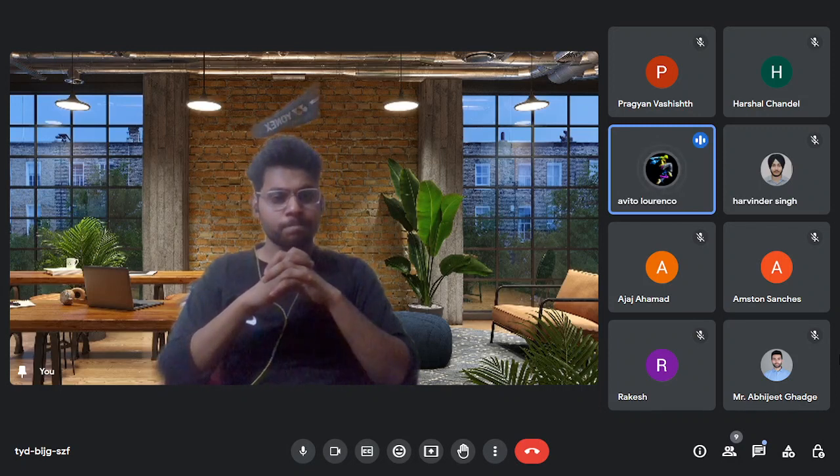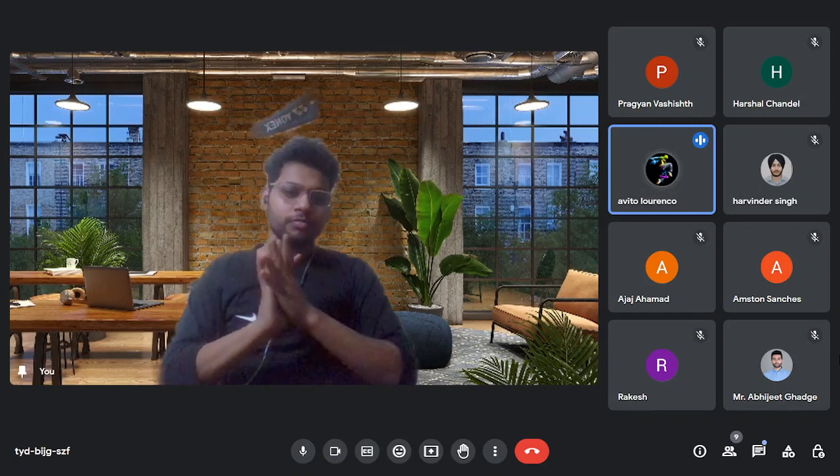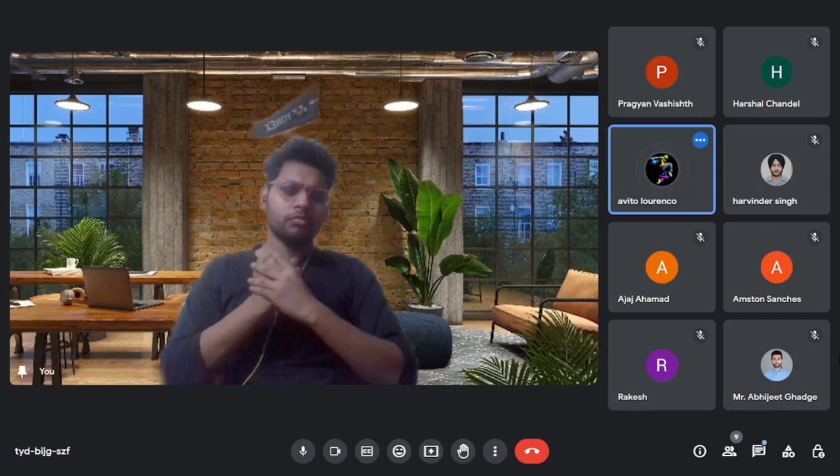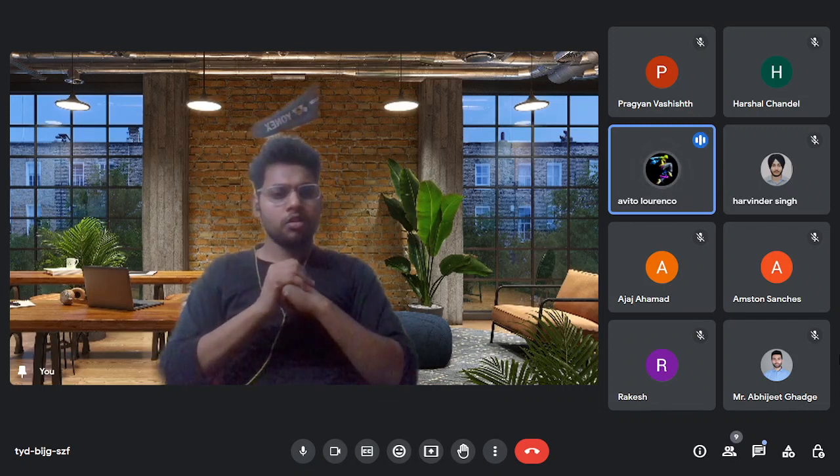They might create some hot spots, and that is when the oil will turn into a small bubble form or mist, and then that can be a fire hazard. But I'm not sure exactly how the oil mist detector is going to detect these small mists of oil, or even where it is located. He mentioned that it might be placed in multiple locations, but we need a proper concrete answer, so we have to definitely look up into that.